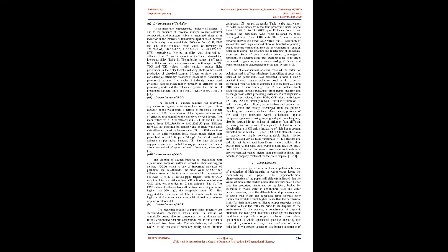than the WHO prescribed tolerance limit of pH value, i.e., 6 to 9 for the paper industry effluent. The discharge of wastewater into water bodies may cause a drop or increase in their pH due to the size and activities of the microbial population. The pH of water is important for the biotic component because most of the plant and animal species can survive only between a narrow pH range, from slightly acidic to slightly alkaline.